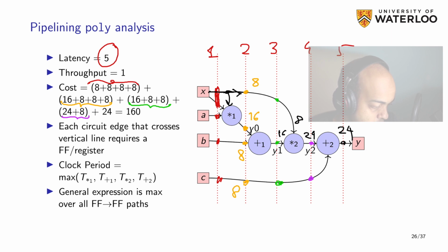Okay. So I'll end up with this entire expression that is going to be the sum of the number of registers I have. I went stage by stage. I calculated how many bits each of these signals takes. I have to apply my multiply add rules with some caution, and then I get my overall register cost here.